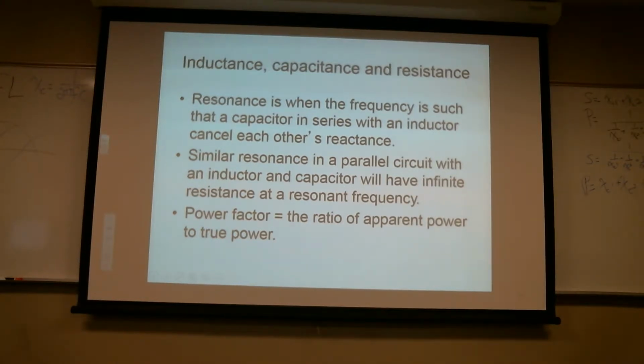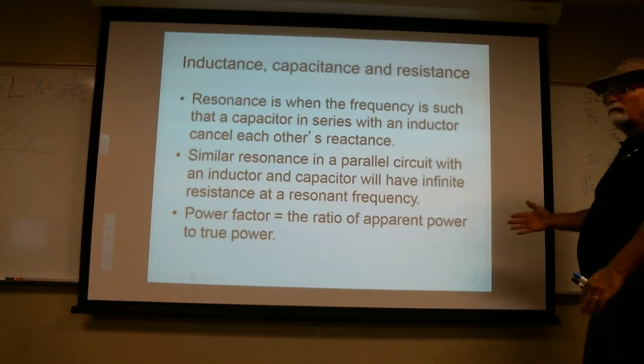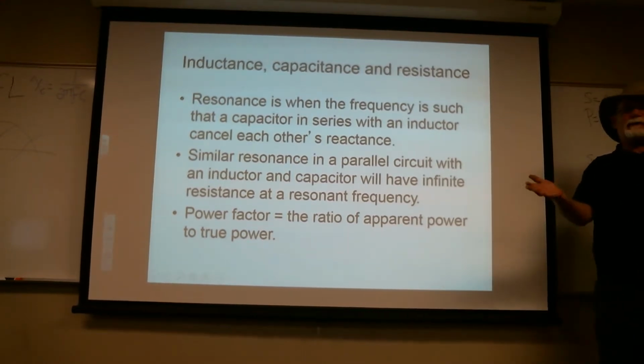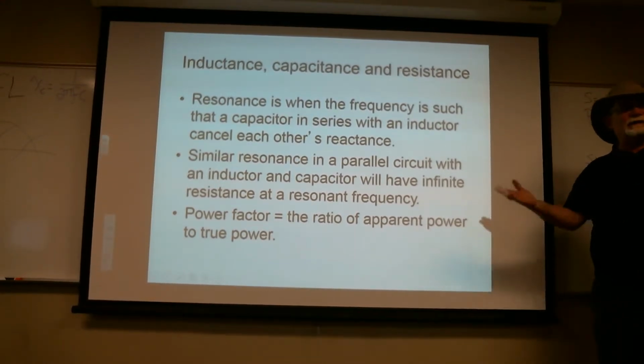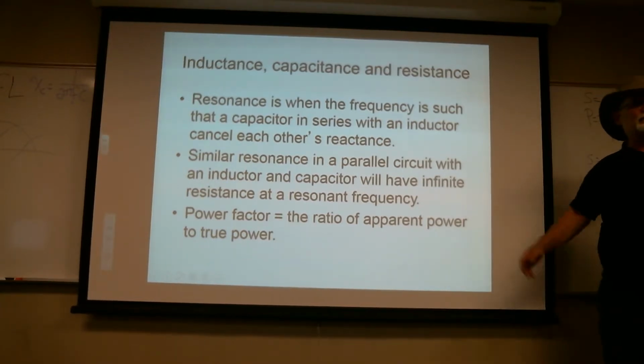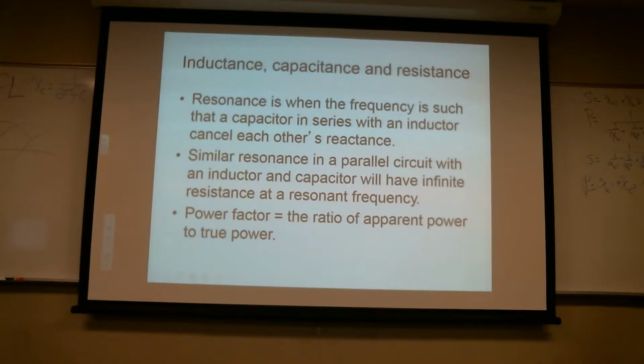Well, the power factor is the ratio of those two expressed in a percent. Okay, so we conveniently got there because I picked 100. But let's say it was 10,000 and 8,900. Well, that would still be a power factor of 89%, right?